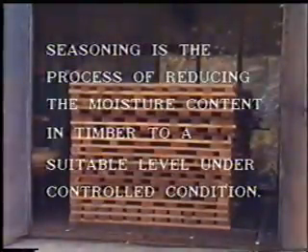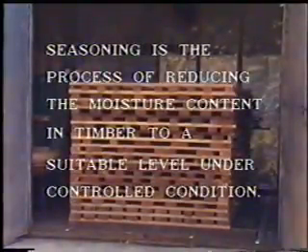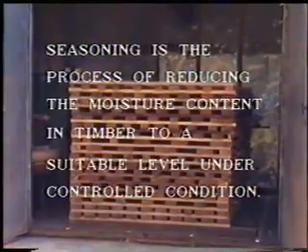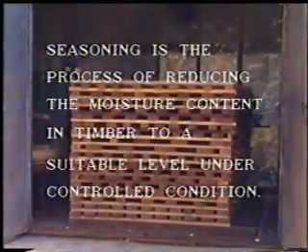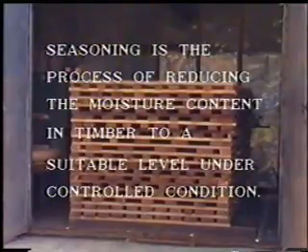Seasoning is the process of reducing moisture content of timber to a suitable level under controlled conditions. In hot and dry climates, timber is kept submerged underwater in log ponds to prevent excessive drying. This is sometimes wrongly named water seasoning. This is not a seasoning process as no reduction in moisture content results.